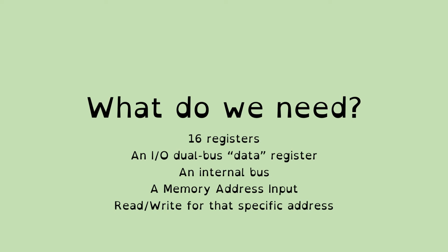register as an intermediary in that process, but we still do need these controls. So we've got a 4-bit number coming in, and we're going to want to route that 4-bit number to one of 16 registers with the control that's coming in. This quite clearly tells me that we need to use binary decoders. So we're going to have a binary decoder for read and a binary decoder for write. It might have been possible to save some hardware here, but once again, for the sake of clarity, we're just going to use two separate binary decoders.